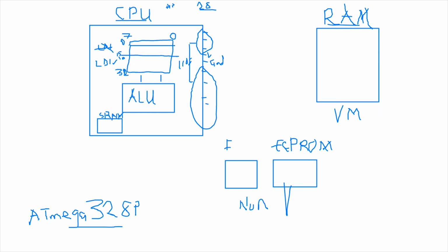Now these groups of pins, once we put 8 of them together, because it's an 8-bit register, you will have a port. Basically, I term it as a portal between the digital world and the physical world, or between the circuitry world and the physical world. For the ATmega328P, we've got 3 of these ports. We've got port D, port C, and port B.